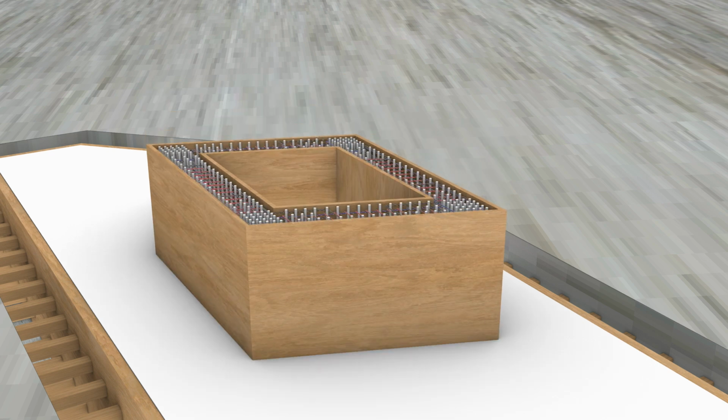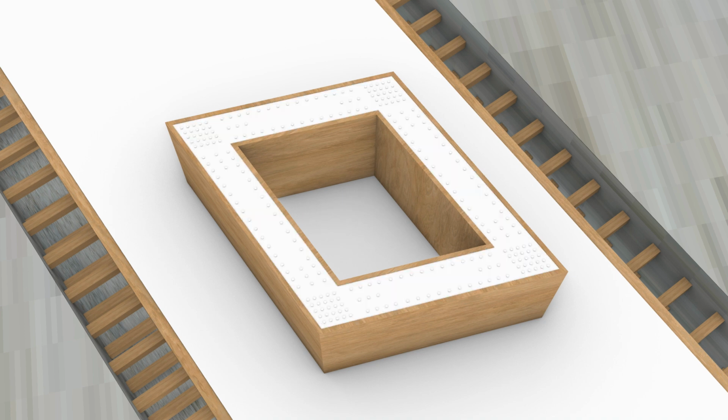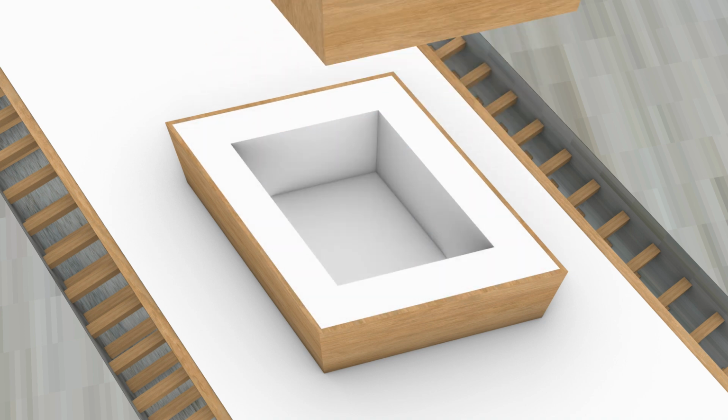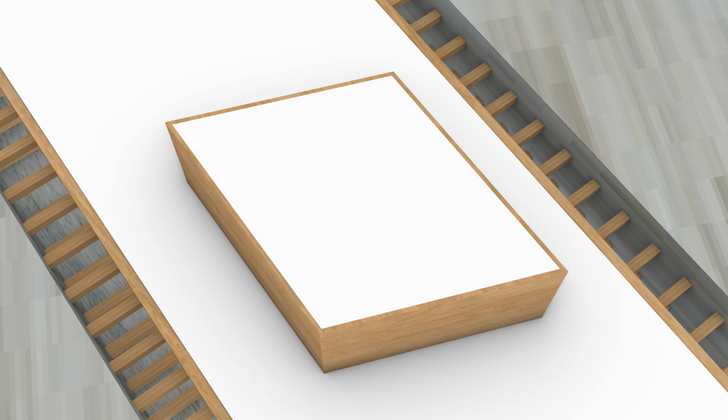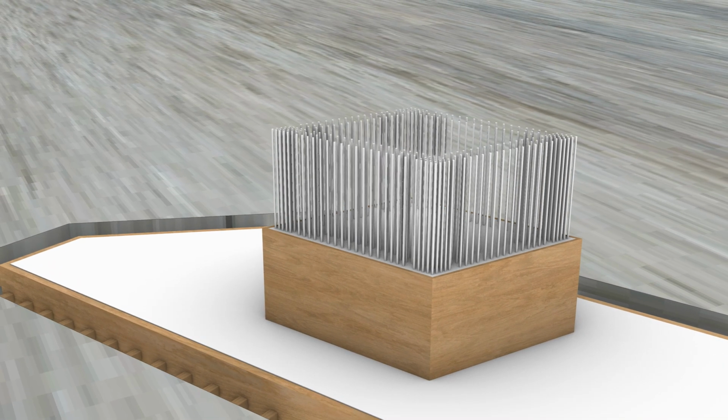After rebar placement, the formwork is installed. The formwork is assembled using prefabricated modular sections, which are positioned around the reinforcements. Once concrete is poured and reaches approximately 70 to 80% of the design strength, workers enter the column interior to dismantle the formwork by sliding it apart. The panels are then lifted out using a tower crane. After the inner formwork is removed, the remaining concrete is poured into the interior of the column.